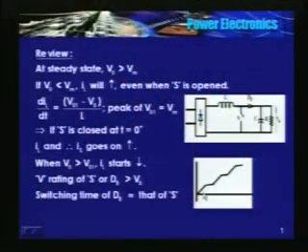in the very first cycle VO is 0, VO1 is positive, so voltage across inductor is still positive, current increases, okay. So therefore if you see, this is current increases. Now when I am opening the switch, whatever the stored energy in the inductor is being dumped to the capacitor, capacitor voltage starts building up, okay.